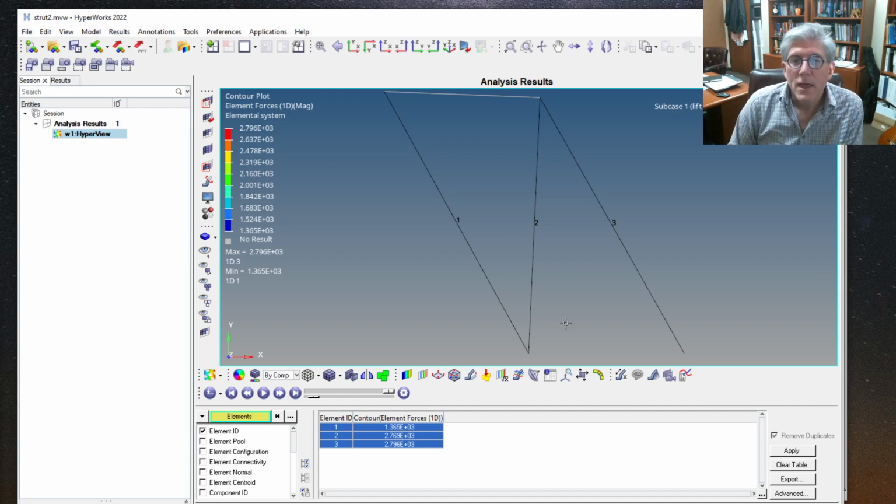But you can check the sign by the stress being negative, so you know that's in compression. And now you can't select the rigid element because the rigid element doesn't deform, and if it doesn't deform, there's no strain, and if there's no strain, there's no stress. So rigid elements can't have stresses, right? If we want to look at the stresses in the wing, we have to model the wing separately, okay? And we'll talk about how to model wings in finite elements later on in the class.